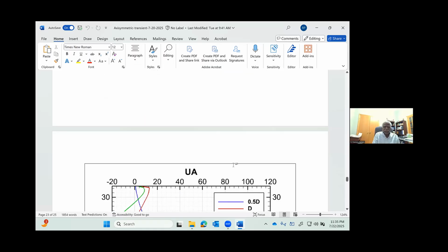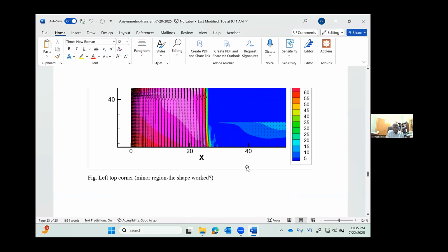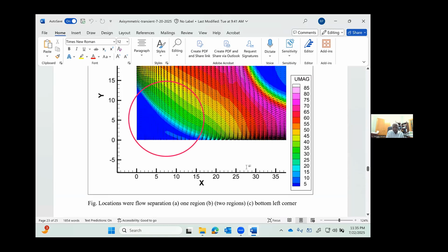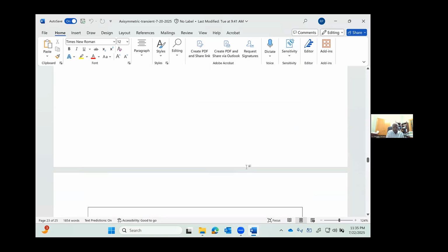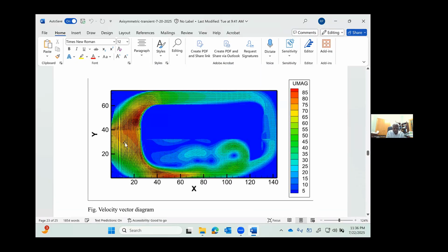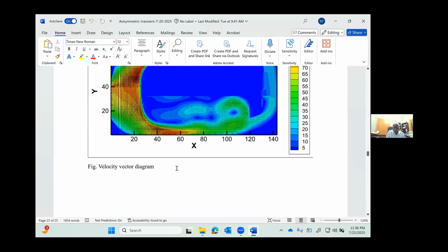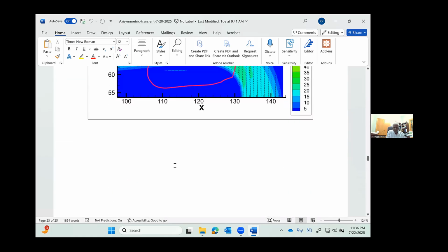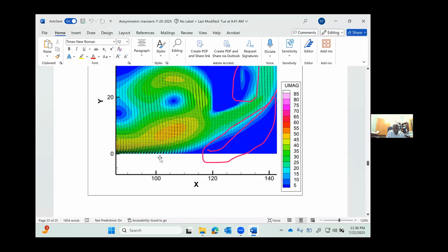The grid resolution, if you wanted to see it, you could see in the velocity vector plots here. You can see the number of points and the resolutions, because when you look at it carefully, we were able to develop the boundary layer very nicely. Look at the refinements and the spacing, so it is able to capture it. All these features are possible only if you can make the grid, and it is a very complex geometry.